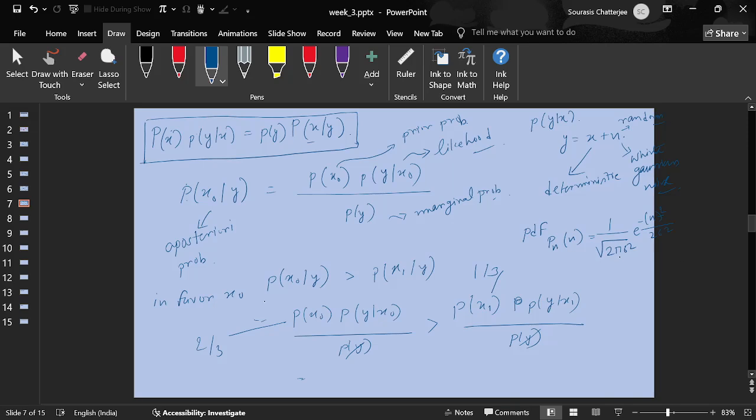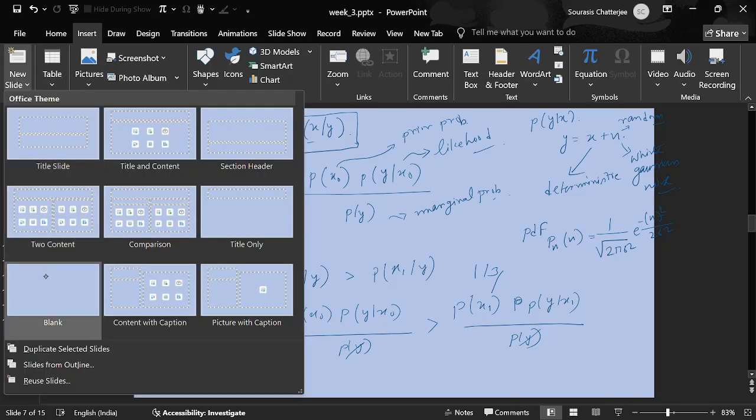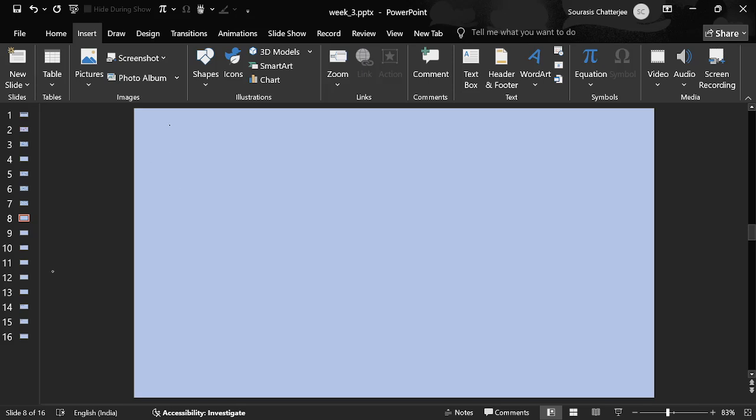So this is the PDF of noise, white Gaussian noise. And the issue is we are talking about finding the likelihood, probability of y given x. So we need another slide here. So we need to find probability of y given x, where y is equal to x plus n. N PDF we already know, pn n, and x is deterministic because we are conditioned on x.